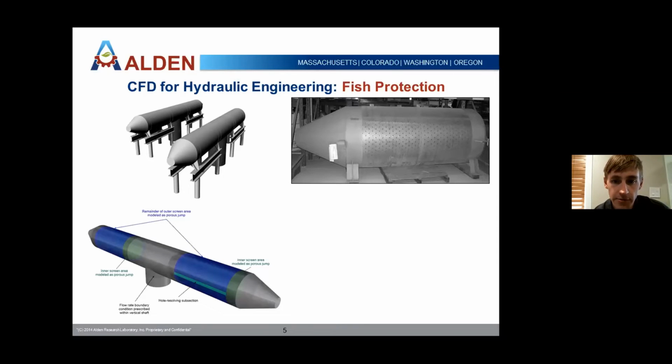So this was actually a Fluent model using an unstructured grid. And I actually did resolve the holes along one strip of this intake screen. And then my compromise, you can't obviously resolve every single one of the holes, was to parameterize the rest of the intake screen using a porous jump. Essentially this is an artificial way in CFD to simulate drag across some kind of, say, porous baffle.